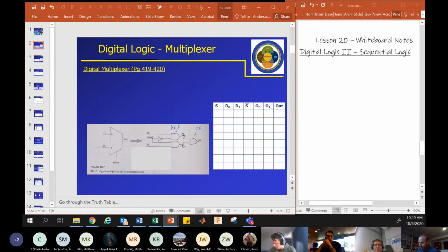Okay, great. So this is a little bit more sophisticated device than what we talked about. It's a certain type of device called a multiplexer, and we'll see why in a second and how it works. But if you see something like this, the question is, how would you figure out what it's doing? How do you know what it's up to? So we'll create this thing. What do we call this thing again? That's on the right. It's the truth table. It is a truth table, yes.